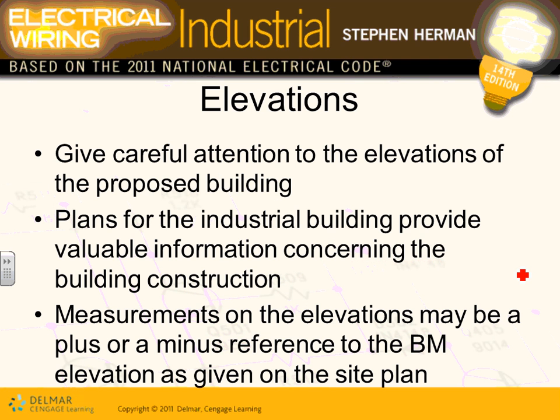Why do we care about the elevation like this? I told you, we need to know how to run our calculation. Careful attention has to be given to the elevations for the proposed building. Derek, you were asking me about your calculation for the lighting. The first thing I'm going to ask, Chad, is what's the structural height and the height of the fixtures for this building? Where are you going to get this info? From the elevation, right in here, gentlemen. Here's the elevation for this building. For example, if I want to find floor 1 and floor 2, floor 1 is located at 751.5 and floor 2 at 765.5. You subtract them from each other, and that gets you the elevation of this floor.